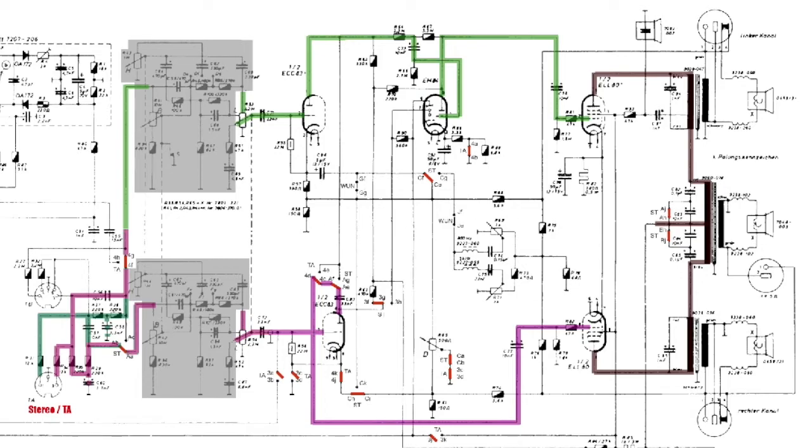There are quite a few other things. There's a feedback path. You remember I mentioned these resistors, this one here and this one here. Now, if you look at this resistor, it comes from this point, it goes up there, and it basically joins the speaker, because this is the external speaker socket. When you plug in a socket, it disconnects the internal speaker, but ultimately this resistor, this path, comes from that speaker. There, down there, through that resistor into that.